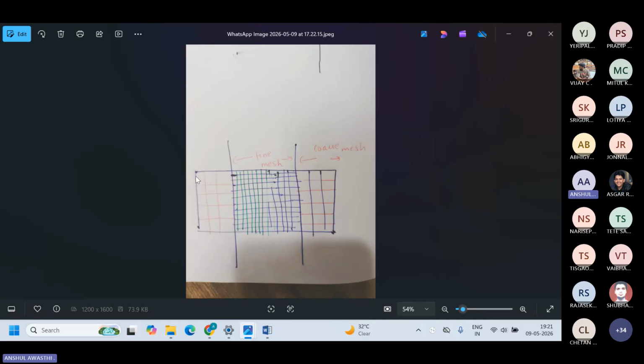For applying the physics equations to this device, I have to break my device into small mesh. This meshing size, you can change. The finer you make your mesh, the more proper results you will get. So meshing is just to apply the physics-based equations to your device.